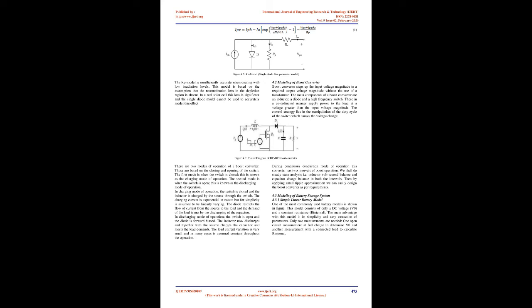Figure 2.9, a typical current voltage curve for a module at 25 degrees Celsius, 77 degrees Fahrenheit, and 85 degrees Celsius, 185 degrees Fahrenheit. This is why modules should not be installed flush against a surface. Air should be allowed to circulate behind the back of each module so its temperature does not rise, reducing its output. An air space of 4 to 6 inches is usually required to provide proper ventilation.